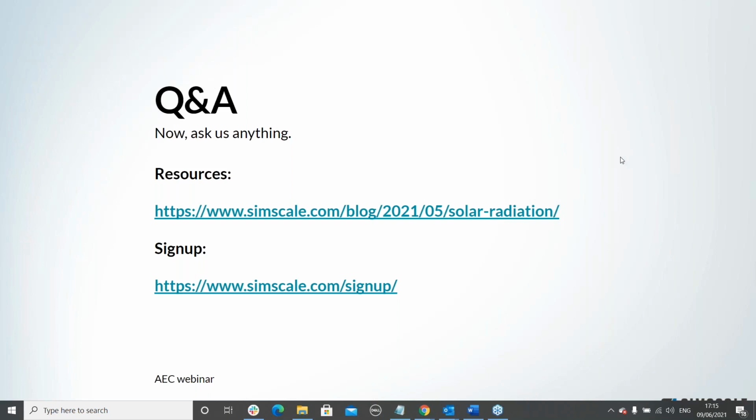So first question, Ajit, I guess is for someone who's going to be doing solar radiation simulation for the first time: how much more time would it take to set up these new features for a simulation? Sure. Once we are familiar with the actual setup for the thermal comfort study, by setting up the boundary conditions, the addition of solar radiation parameters is just going to take a couple of minutes.